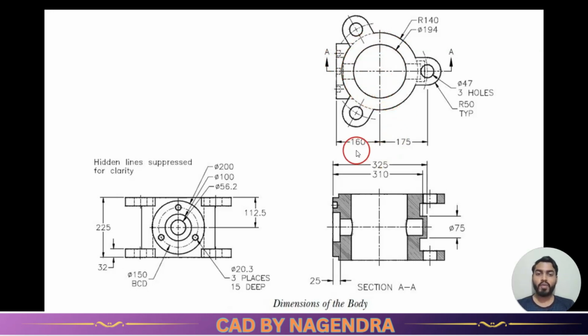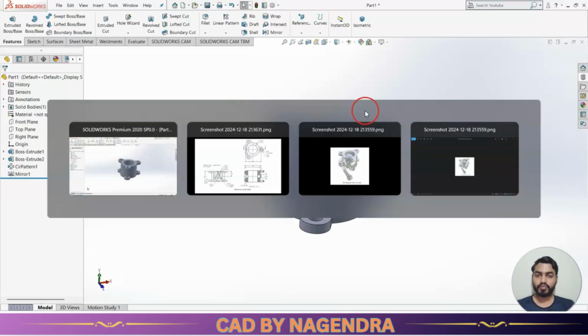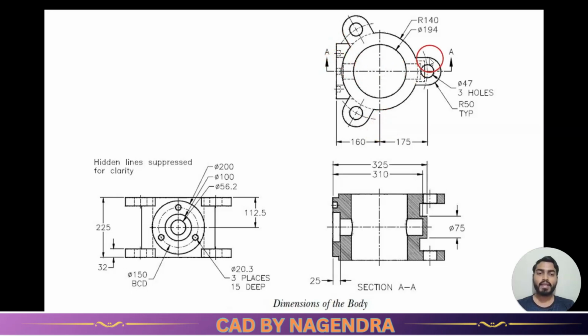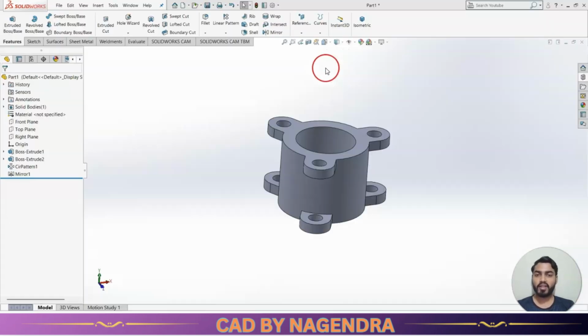One more is, with this distance we can create one offset plane. Later we will draw the shape and we will make it extruded boss up to next. So now we are going to create that reference plane, a lengthy process only, because we will be using different type of options. Now this profile should be exactly opposite to this horizontal one.